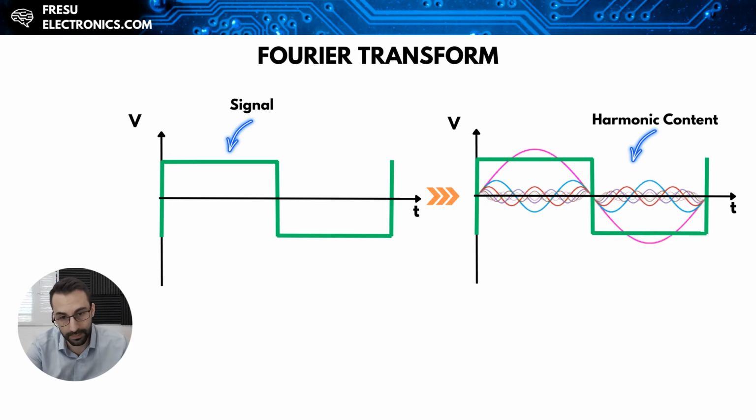In fact, the sharper the signal, the more high energy harmonic content there is, and the more high energy harmonic content, the more energy there is. And the problem with this high energy harmonic content is that the energy contained in these harmonics needs to be contained and then controlled in order to avoid emissions and to channel the energy where it actually needs to go. And after all, what we're measuring with the EMC test is exactly how this energy moves and how high or above the imposed limits this energy is.